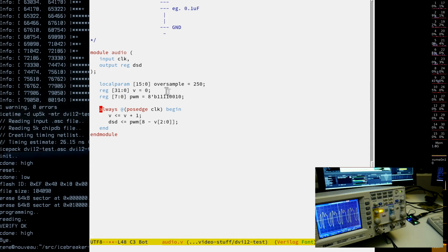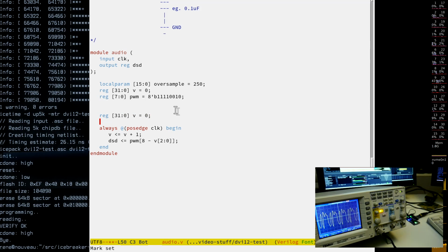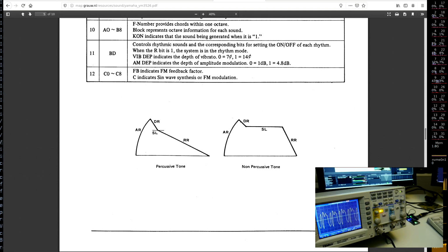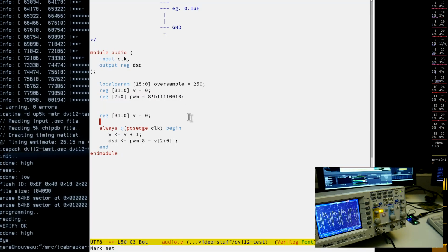We don't need such a high frequency, maybe later we need to check what sounds the best on this poor man's DAC. So next we would need to have some generators for this. We would also, by the way, for these generators need an envelope generator, envelope meaning this stuff here, and then some frequency based on this.